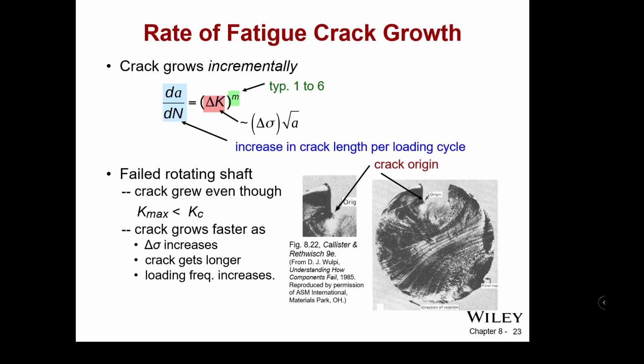The crack gets longer, and the loading frequency increases, especially for something that has to rock back and forth or oscillate. That can be very, very key. So it gives you the idea of the direction of rotation, and you can see that in the curved lines. So the direction of the rotation is in this general direction. So it's a counterclockwise rotational direction, and then the final rupture is here at the base.